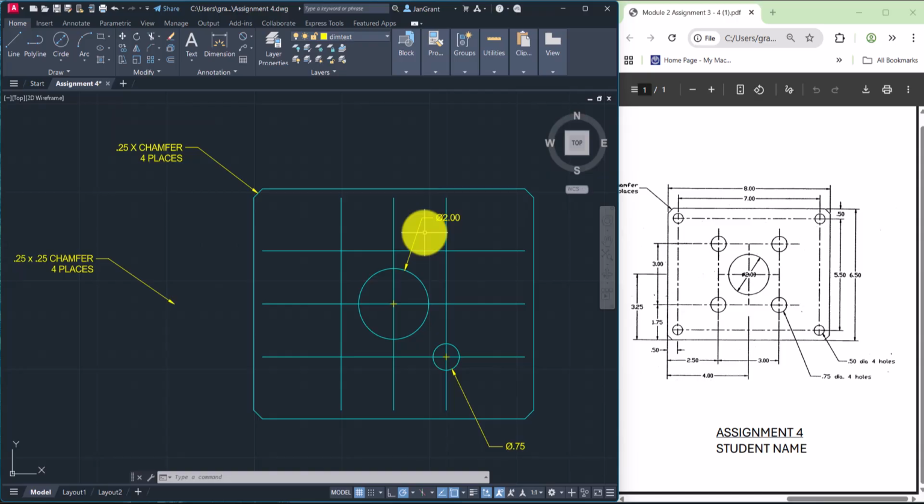Something else I wanted to point out to you is that to move objects on the right layer, you can click on the object, drop the list down, and put it on the right layer. So these are center lines. I'm going to click on center line. Also, we can use these little blue grips to stretch these lines back. You see how these lines right here are not as long as they are when you create the offset. So you can use these blue little grips to stretch the line back.